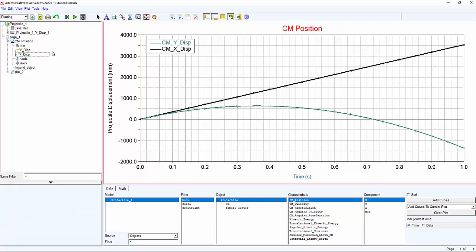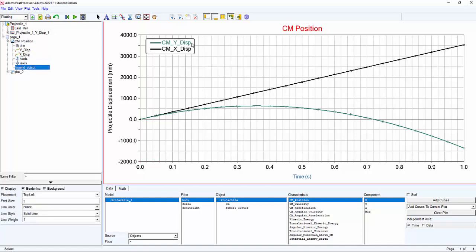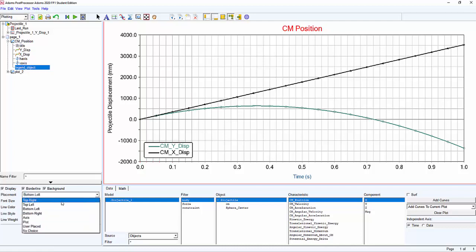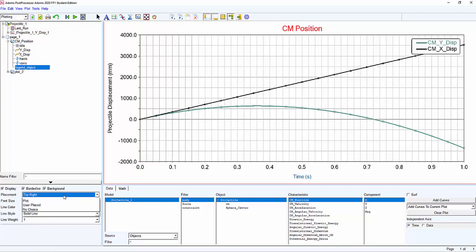So now, as you can see, I have full customization for my plot. You can also change the position of the legend. In a curve like this, the position is good. Sometimes you would like to make it down or up, so you can click on legend right here and then select the position. You can make it top left or bottom left or top right or bottom right.